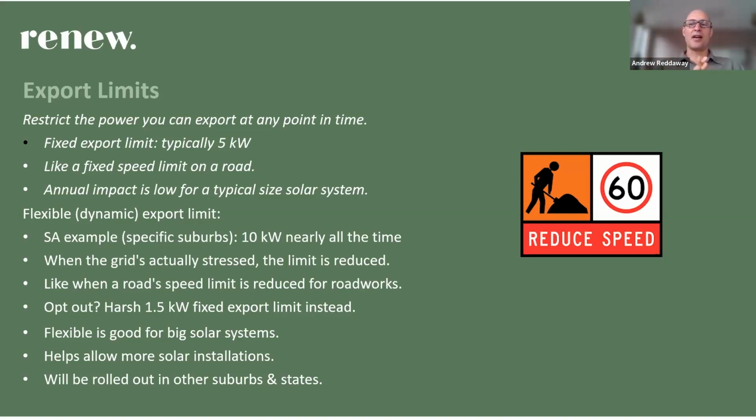So you're only going to get 6 kilowatts out of those 13 panels under those conditions. Most of the time they'll be generating more like 2, 3, 4, 5 kilowatts, right? Because the angle's wrong or there's shade or whatever. So that's the first thing to be aware of.